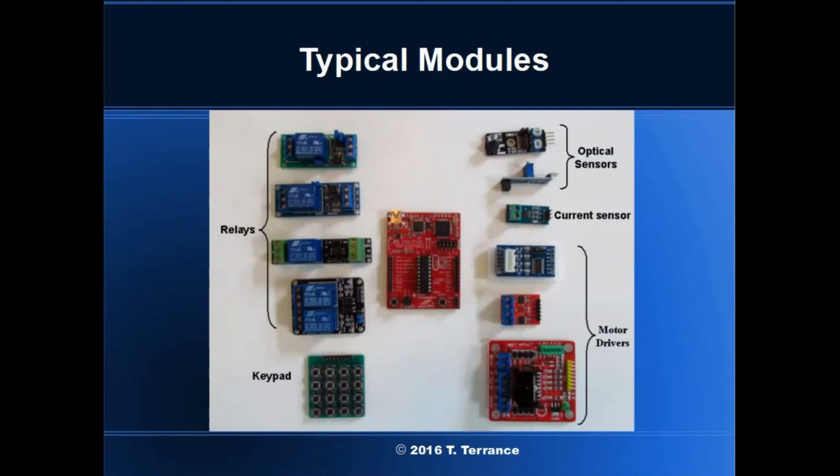Starting in the upper left-hand corner are some relay modules. These can be had in 1, 2, 4, 8, even 12 relays per. These modules are an exception to the rule that these modules operate on 5 volts. They come in 5 volt and 12 volt varieties, maybe more than that. For interfacing to a microcontroller, choose the 5 volt variety. Also watch the rating of the relay contacts, in most cases they can handle more amps than you are likely to use on a model railroad.